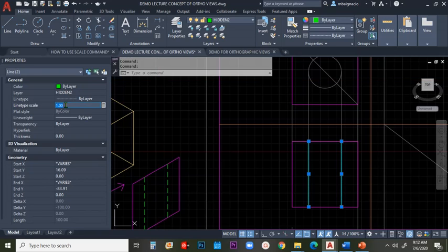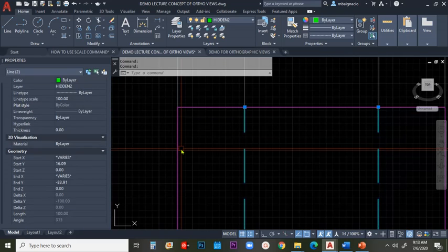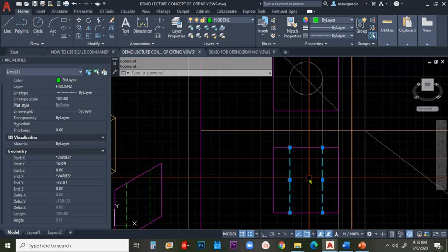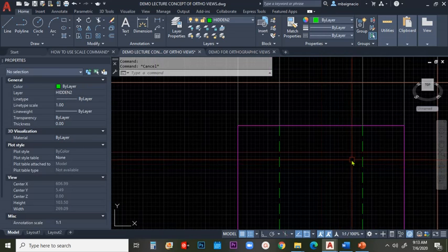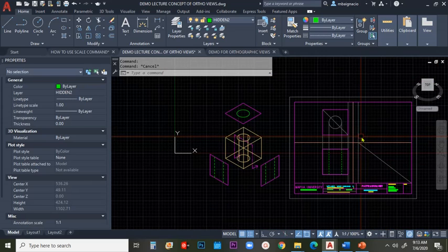Okay, and then let's start working with 10. Automatic, you can preview the changes of the scale. So maybe I'll start with 10 and then increase it to 100. Now you have already a working preview, but here I might use 50. Okay, so that the gap in between the hidden line will be just sufficient in the representation of our hidden line. Okay, now next, moving on.